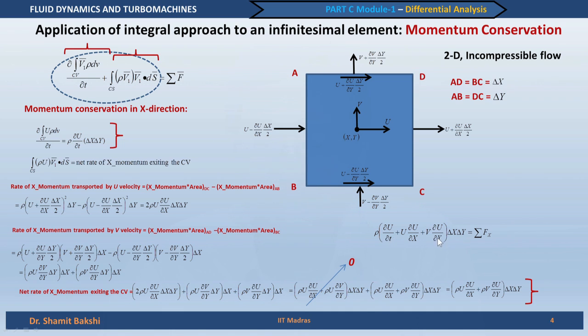So, by doing all this, what we have got is an expression for acceleration. This part is actually the acceleration of the flow written in terms of the Eulerian velocity. We know acceleration is the rate of change of velocity with time, so in that sense we can write it as a derivative like this.